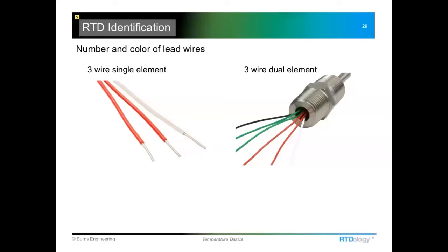On the other hand, it can also go up, and that would typically be caused by high vibration or shock, and that work hardens the platinum wire, which increases its resistance, and so you're going to see a higher than actual temperature indicated. So PRTs, PT100, RTD, they can go up or down. And it's kind of a 50-50 mix of what I see.